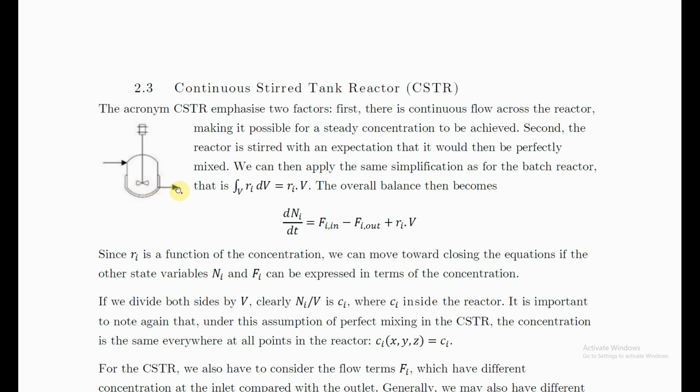So after the first instant where you form 99 moles per cubic meter of product, after the system reaches its steady state, there's only a tiny fraction of component A here. And so you're sort of a victim of your own success here. You manage to convert so much of the reactant so quickly that the concentration here is going to be so low that your production rate is going to be extremely low.